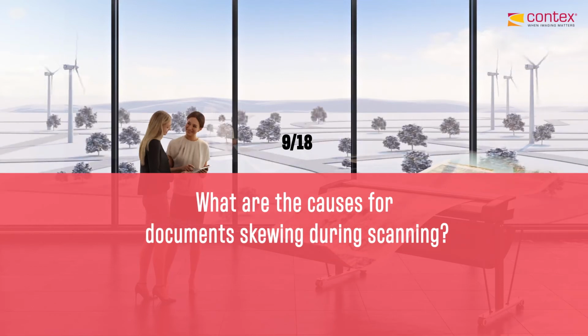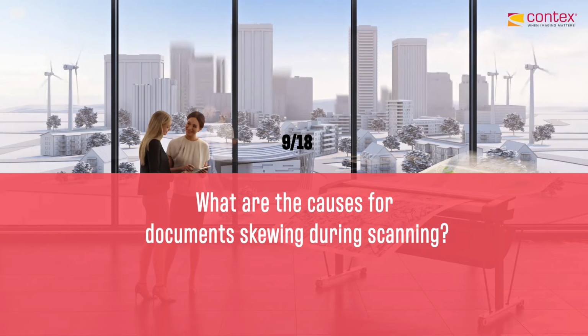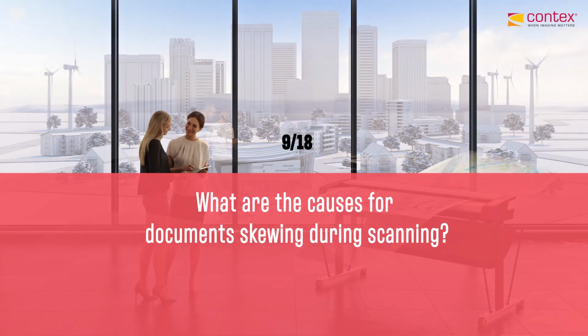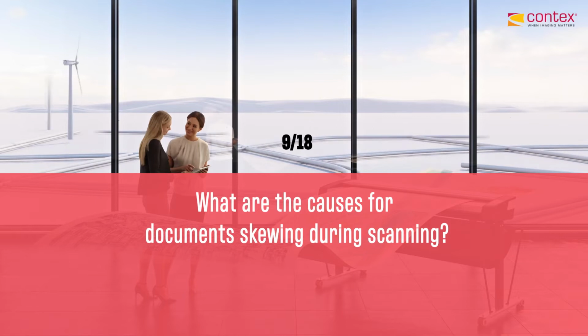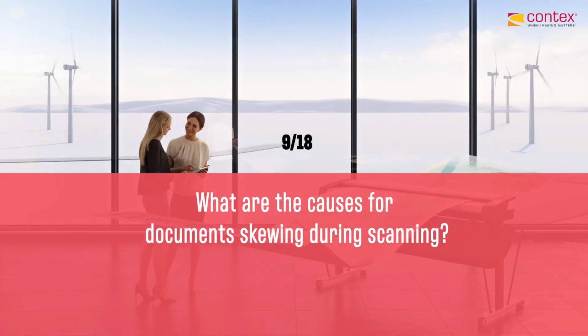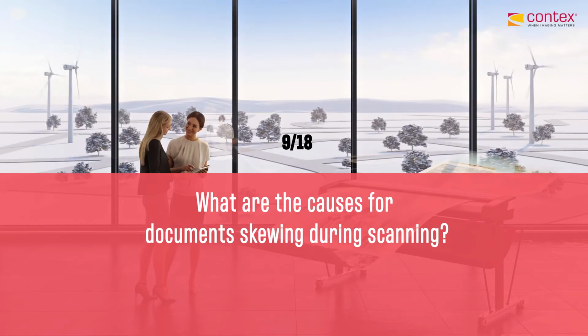And that's where you were saying you can open it and have the motor advance and just hold the cloth on the roller. Right. It's the fastest, simplest way to clean a feed roller. It gets the whole roller, and you're not sitting there pushing the roller trying to get one little spot. Yep. It's almost like lathing the dirt down off of that one roller. Yeah, and it's so much faster. You can clean all the rollers in a matter of a minute. Well, I think especially if you come back with a clean cloth, you can see right away.